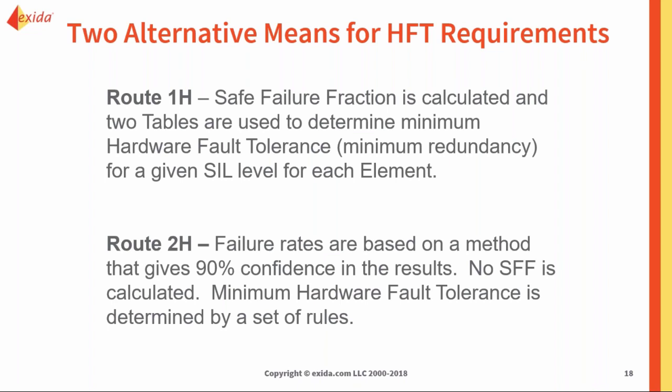And Route 2H is based on more reliability data. We're looking at more proven in use. Has this part been out for a very long time? Is it a ball valve that really hasn't changed in the last 20 years and you really haven't had any issues with it?